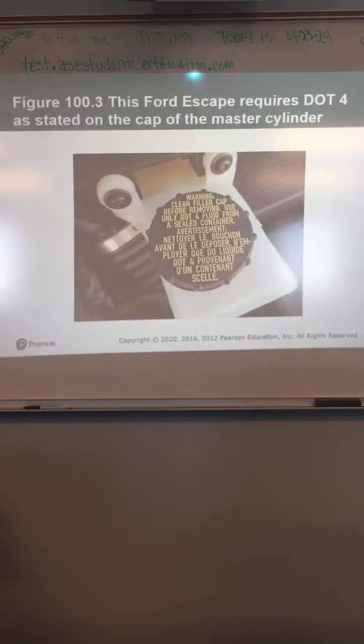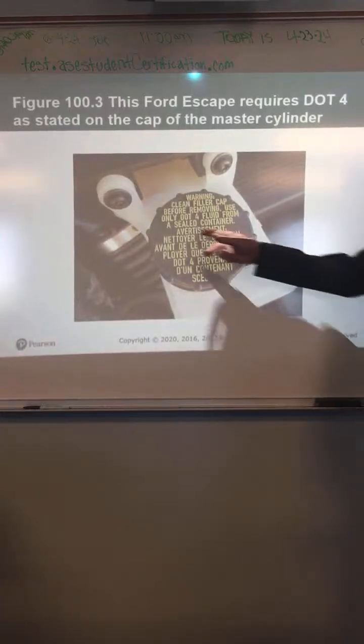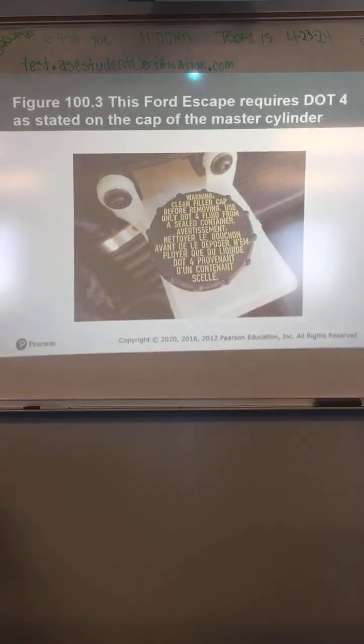On the cap of the master cylinder, it's going to tell you what it wants, okay? Always use whatever fluid this particular vehicle wants, whether it's coolant, oil, power steering fluid, brake fluid, whatever it is. Just make sure you use the proper fluids. In this particular case, this one wants only DOT 4 fluid from a sealed container. It even says that on the cap, from a sealed container, okay? They're very specific about that.